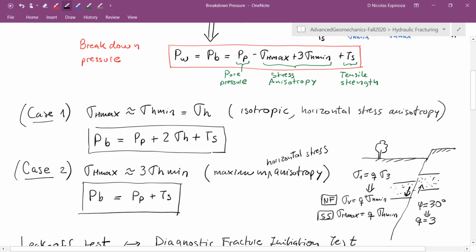And this comes from the reasoning of the equilibrium of faults, and assuming that the maximum effective principal stress is a function of the minimum effective principal stress and the friction parameter q, which implies that this place is under the limit of the maximum horizontal stress or the minimum horizontal stress, which is the result of the equilibrium in faults.